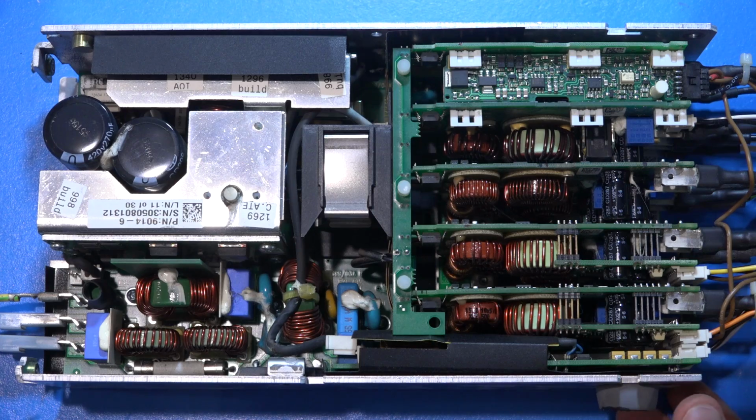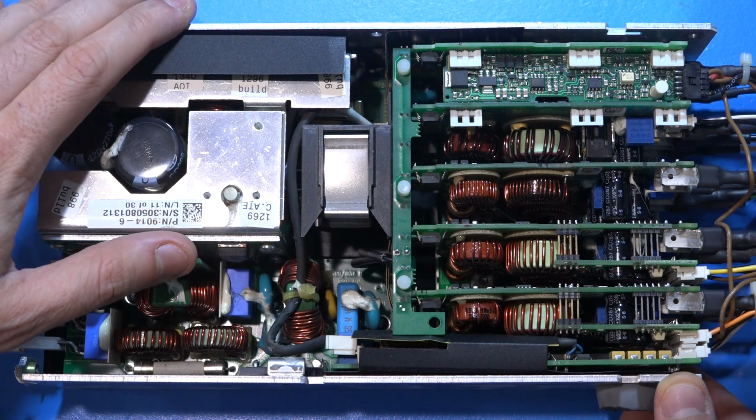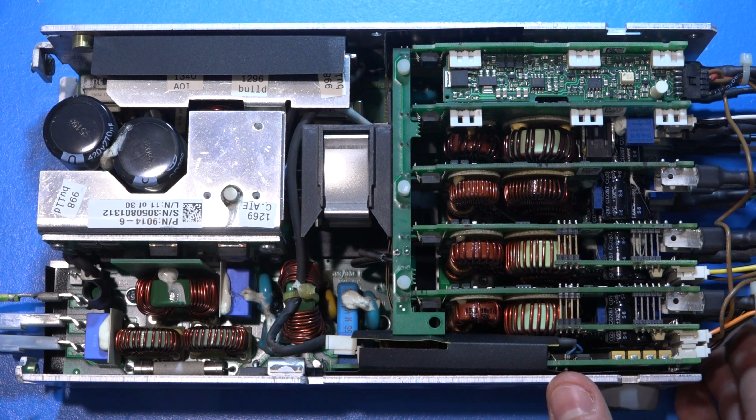That's why there's absolutely no sign of life, is because the AC line is just not getting in. So I'm going to try and remove all of this and see if we can reduce this power supply as much as possible to its fundamental building blocks, which is the main front end, rectifier, and DC-DC converter portion, getting rid of all of these and finding out what has caused the fuse to die.